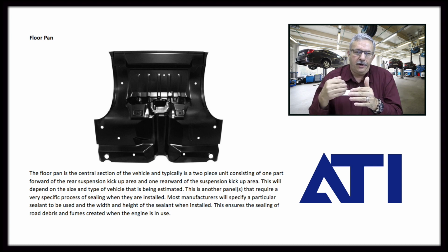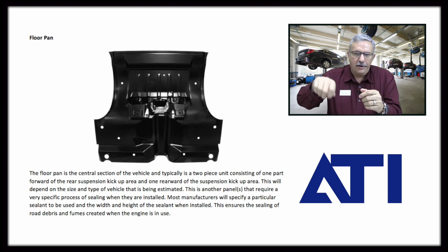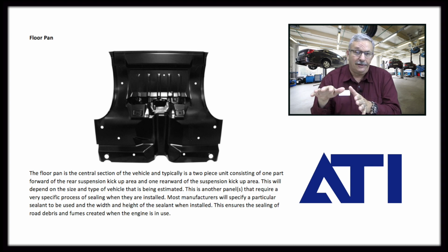So we've got to make sure, and this is the consideration in the repair plan, how long will it take for me to make that part look like it did previously? And I'm not talking about putting plastic on it and sanding it down and sculpting it so it looks right. I'm talking about a hammer and a dolly, a slapping spoon, you know, anything that's required to move the structure back to its pre-loss position. So it's not only the shape, but it's the state of the metal that we've got. It's two things we're looking at here, the shape and the state.